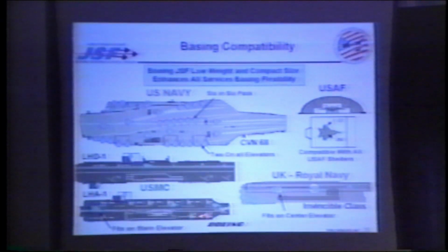In terms of the Marines airplane, it is fully compatible with both LHD and LHA performance requirements. We can also, again, spot this airplane on the stern elevator on the LHA without a wing fold. And then finally, for the UK Royal Navy airplane, that airplane is the same airplane as what we envisioned for the US Marine Corps. That will spot on the same spot lines as the Sea Harrier. It will also fit the centerline elevator on the Invincible class ships without a wing fold.